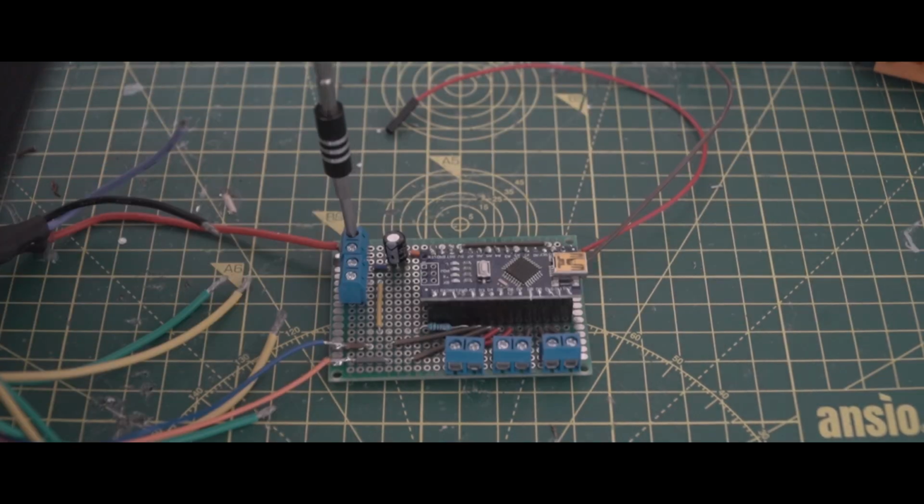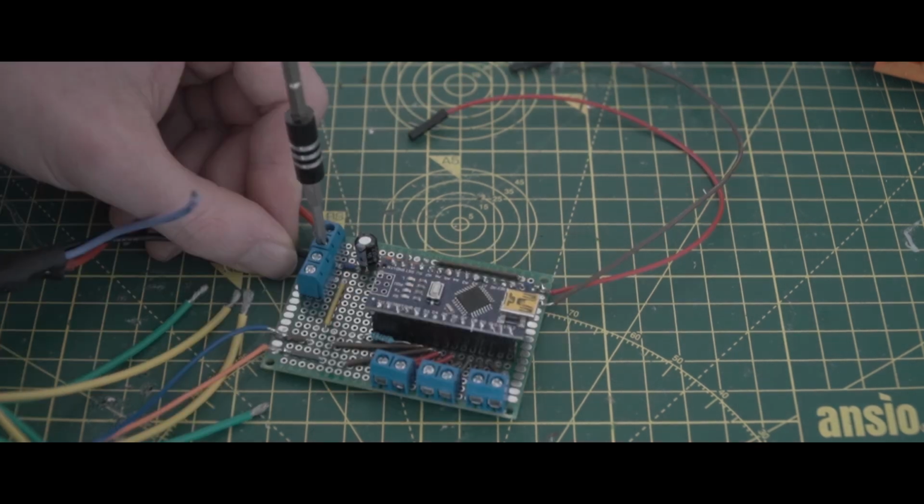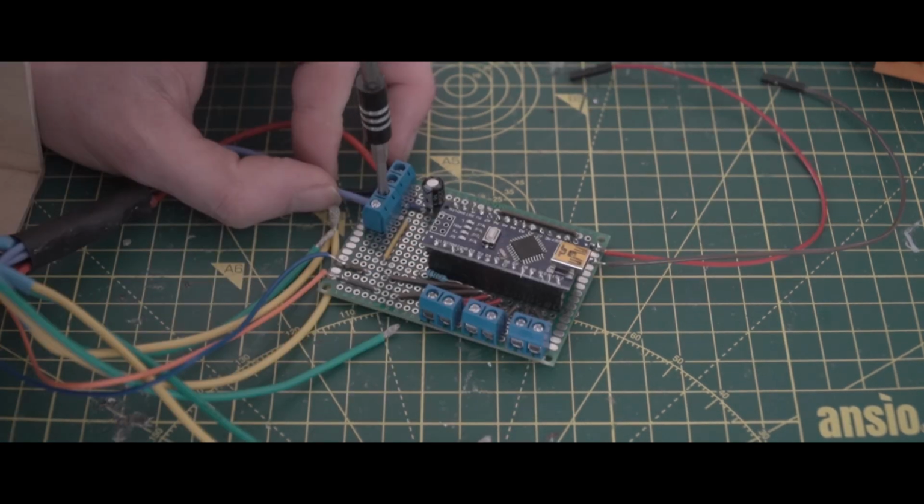Power is supplied to the LED strips through the 5V output and ground pins on the Arduino, while data is fed from digital pin 2. Each of these lines is split in parallel to each of the 3 LED strips, allowing them to receive power and data at the same time and remain in sync.